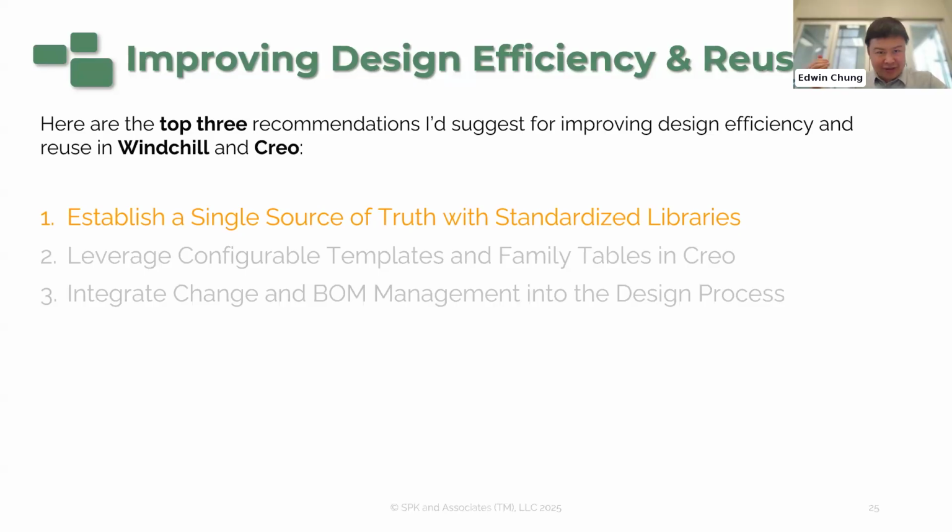Establishing a single source of truth, right? First, you should centralize all your CAD models, parts, and product data within Windchill PLM so engineers can always access the latest approved version. Build and maintain standardized libraries of frequently used components, like screws in Creo. Again, these should be managed through Windchill so that everyone's reusing the same part to reduce duplicate part creation, ensure consistency, and accelerate design cycles. You should leverage configurable templates, right?